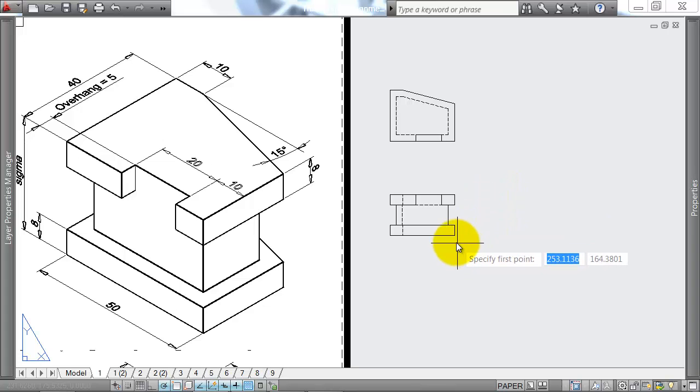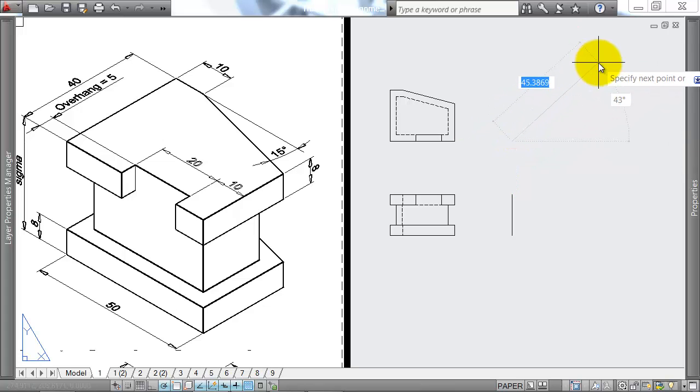Okay, now what do we have next? If I drag this out over here, I can start to put in my last view. So this one's going to have the same height as the view next to it, and it's going to have the same depth as this object has in terms of its height, I guess. So I'm going to run this line up here and this one over here. I'm going to draw a line of some distance at an angle of 45 degrees.